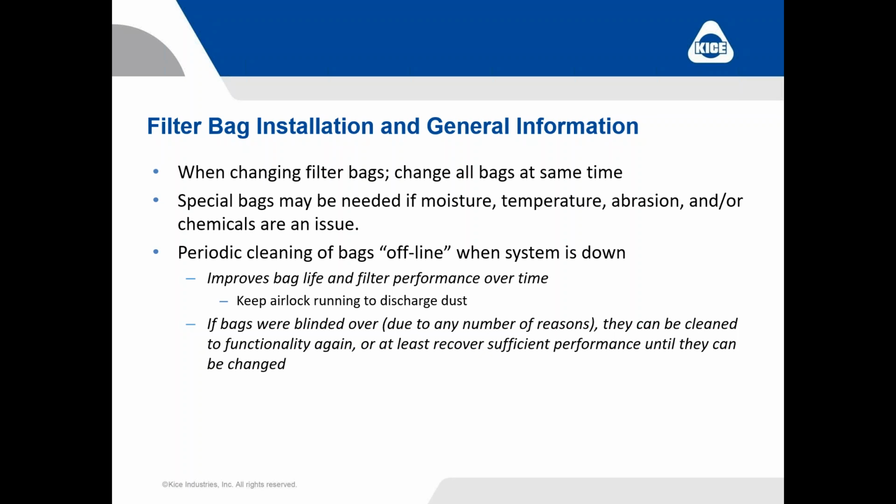And something I'll touch on, I think, one or two more times before we're done, is periodic cleaning of the bags offline. Now, what I mean by that is, in a nutshell, I would like to see you turn the suction fan off on the baghouse, but leave your cleaning mechanism running for 5 minutes, 10 minutes. Take the air away from the baghouse so that you're not pulling more dust to the baghouse, but give that cleaning mechanism time to run a few cycles, knock the dust off of those bags, and get those bags cleaned off.